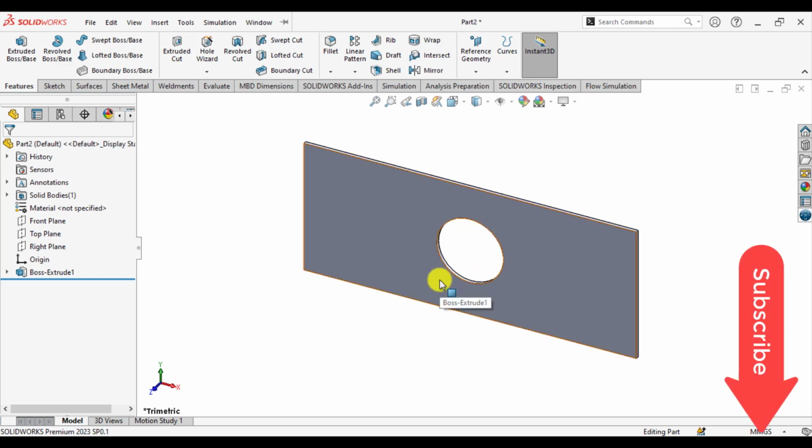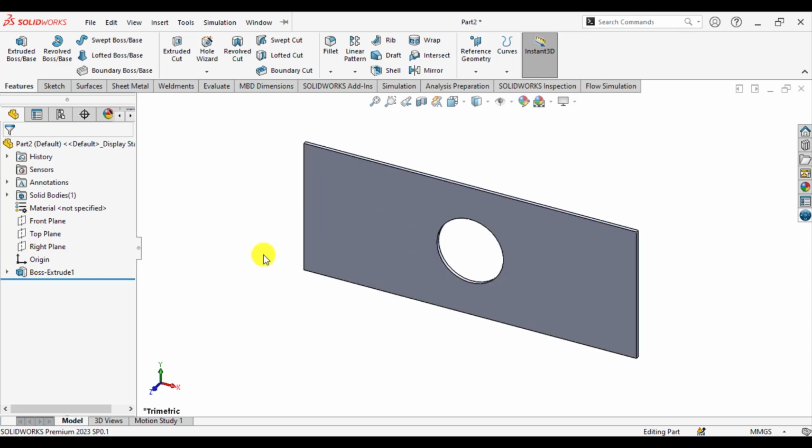In the first step, we will make a full model, then execute its simulation study, then we'll evaluate its results. After that, we will make another configuration of a symmetric model. Then again, we will carry out simulations and compare the results of both symmetric and asymmetric simulations.